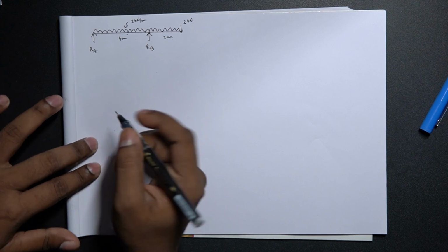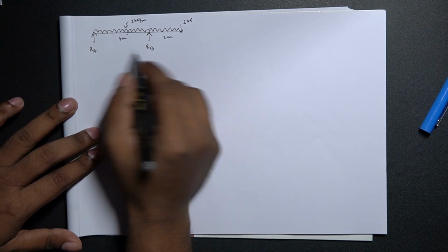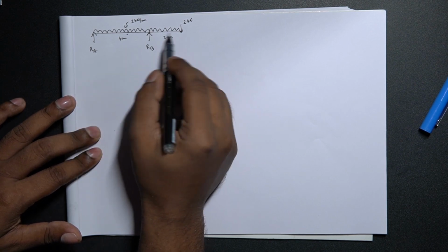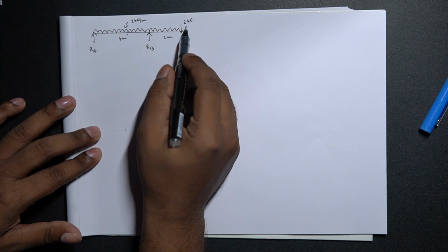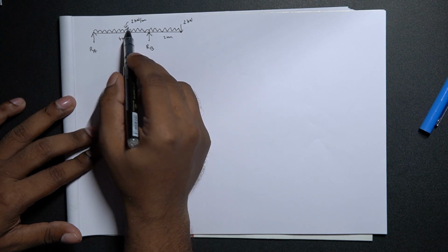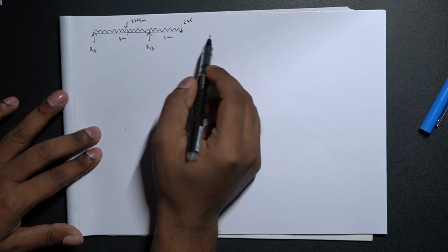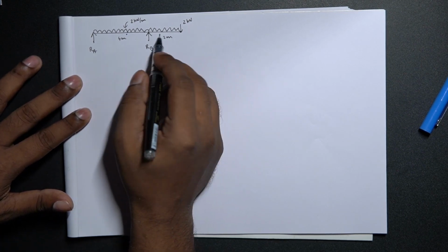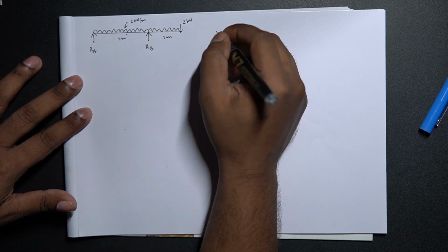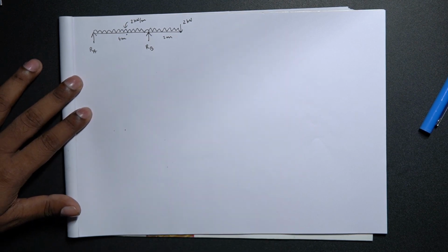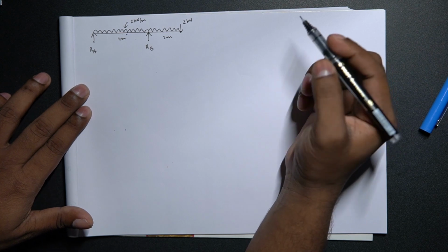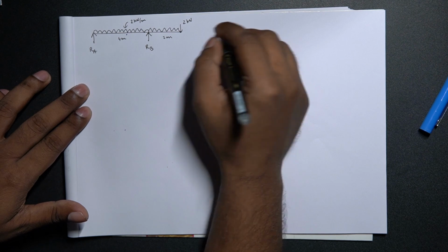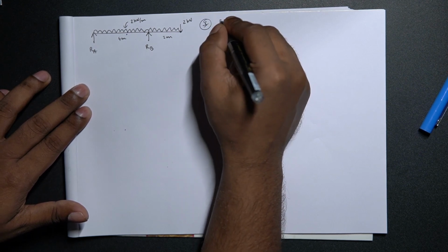So let's solve another example here. We have an overhanging beam with 2 supports RA and RB with an overhanging portion of 2 meters outside RB. We have a point load of 2 kilonewtons and a UDL of 2 kilonewton per meter all across the beam. The entire span of the beam is 4 plus 2, 6 meters in total. So let's calculate the shear force, bending moment, maximum bending moment, and represent that in an SFD and a BMD diagram. Starting the first step, let's calculate the reactions.